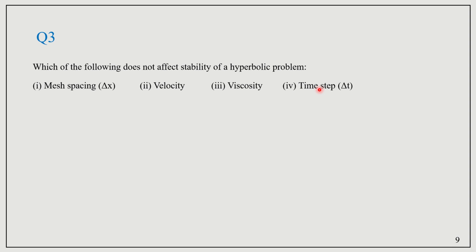What those numbers or conditions depend on is velocity, time step, mesh spacing, and time stepping. If we take the Courant number itself, it will mostly be a function of velocity, delta t, and delta x. We put a certain condition such that the Courant number must be less than a given value. Mostly it will be v times delta t by delta x, and powers may vary.